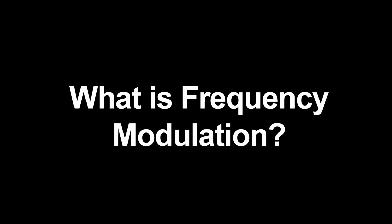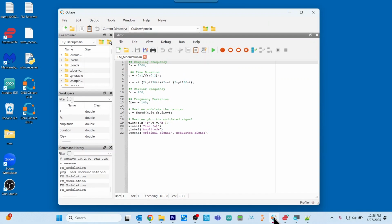perform an FM modulation. So let's look at the screen here. We want to point out that we have a sampling frequency of 1000. We can skip over the time duration for now. Line number 7, where X equals, what we're doing is basically just adding up 2 sine waves. On the next line, we have a carrier frequency of 200, and this is in hertz.